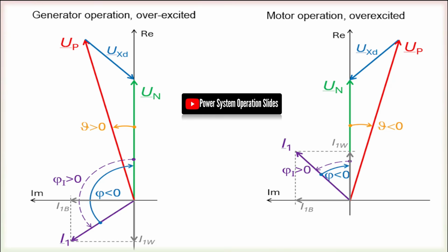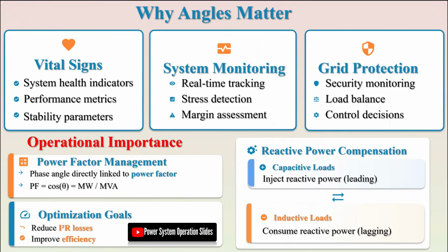The revolutionary solution came in the form of GPS-synchronized time stamps, enabling synchrophasor technology through phasor measurement units (PMUs). These devices provide perfectly time-synchronized measurements of voltage magnitude and angle at multiple locations, using the GPS signal as a universal time reference. This allows meaningful comparison of angles measured at substations hundreds or thousands of miles apart, providing unprecedented visibility into the grid's dynamic angular behavior.